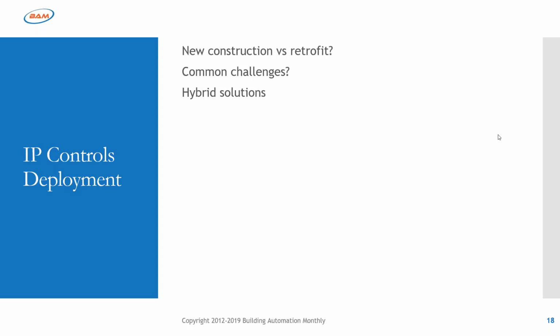Everyone does MSTP differently. The business side of MSTP is proprietary. Yeah, kinda, sorta. I mean, MSTP as a signaling profile or protocol is pretty much standardized. If you want to be BTL compliant, you've got to have at least the common services and objects implemented.